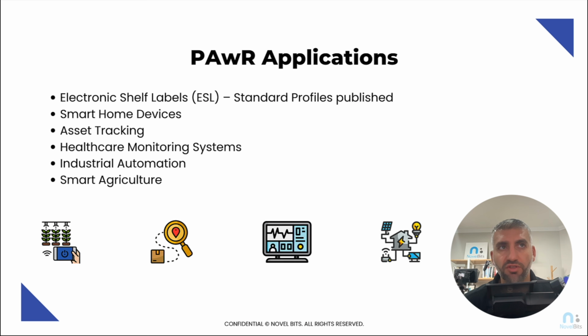Previously, before the introduction of this, a lot of people, if they really wanted to use Bluetooth Low Energy to solve a problem that was more mesh-like, that was kind of like what we are talking about here, say, for example, ESL, they would try to solve that with Bluetooth Mesh. Unfortunately, Bluetooth Mesh is not power friendly at all. Current consumption, and the way that Bluetooth Mesh works, by the radio being on all the time to listen and to send, especially in the case of relays, it is not very practical, and it's not really suitable for this kind of application.